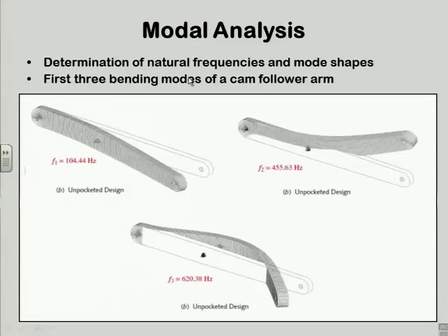So here's another thing we can do with FEA. This is a different issue altogether, called modal analysis, the fancy name for finding the natural frequencies and more. By modes is meant the shapes of how it bends when it vibrates. And there'll be a whole bunch of these modes, you know, first harmonic, second, third, fourth, etc. And they won't be equispaced in frequency either. They will not be double, triple, quadruple. They'll be in some staggered increments. And they're all shown here in hertz.